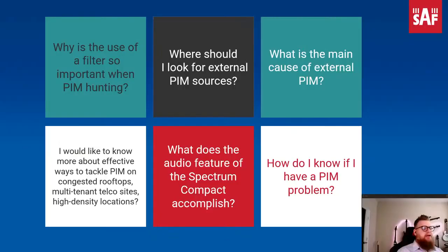you have a sense of proximity with the tone. It sounds very much like a theremin. As you get closer, the pitch increases, and this is all dependent on your settings. Keep in mind, you've got the squelch line and then the max line. Within that window, the pitch will increase or decrease depending on how far away you are from the PIM source. And you don't even have to look at the screen to verify that.